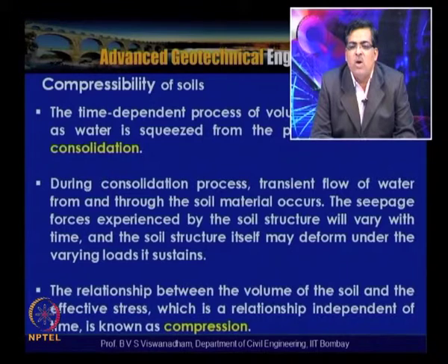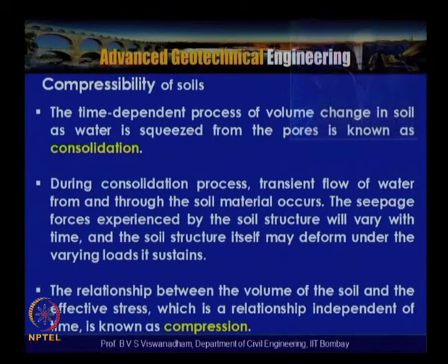So, the relationship between the volume of the soil and the effective stress, which is independent of time, is known as compression. That means the relationship between the change in volume of soil, which is nothing but the change in void ratio, and the effective stress, independent of time, is basically known as compression.